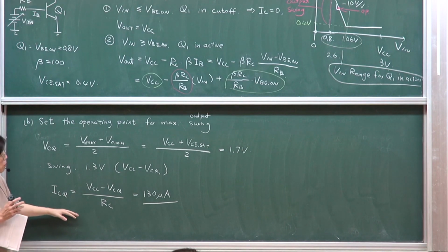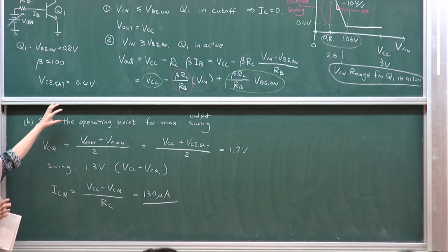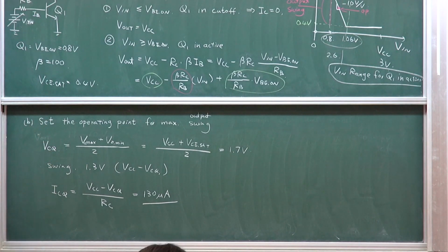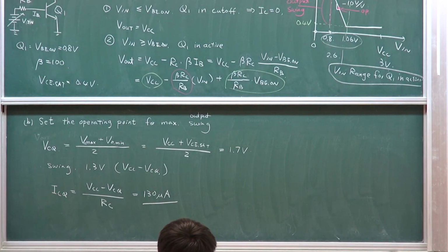But if my output is going to be amplified to a large level, my input voltage will not be very small, then you have to consider setting it to a more appropriate position, allowing the signal to be completely amplified without significant distortion, as I said, when you're standing at the edge.